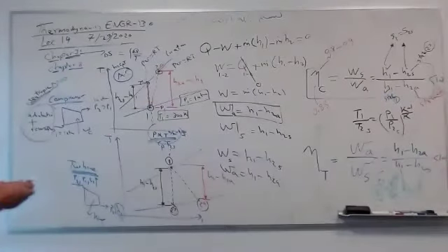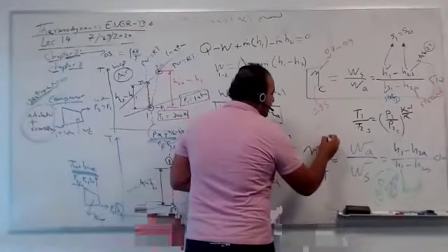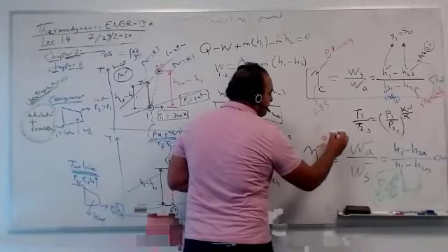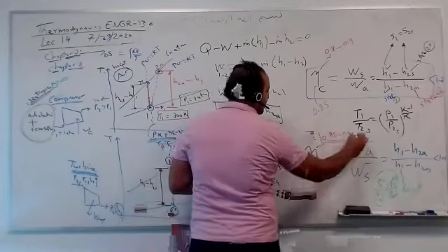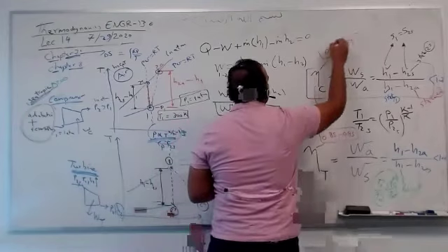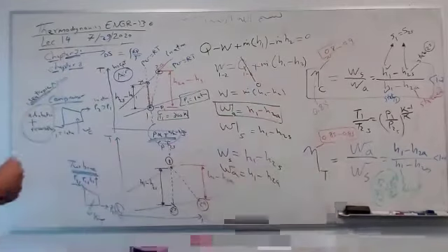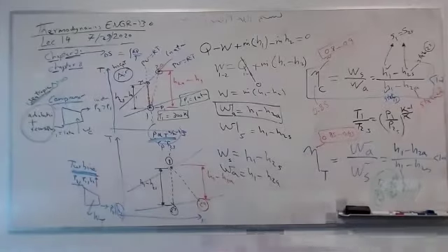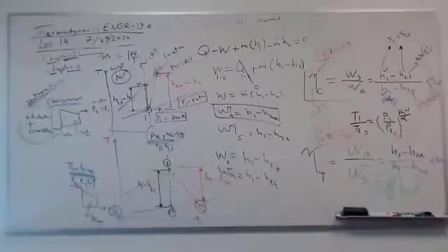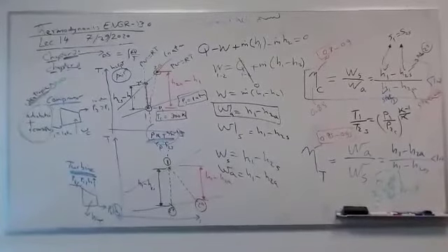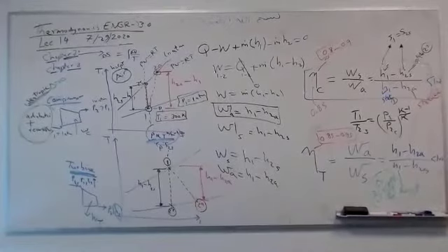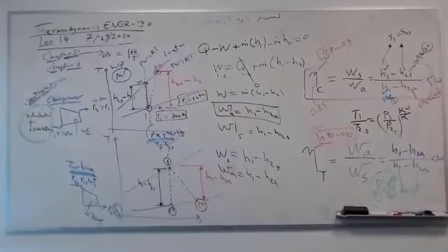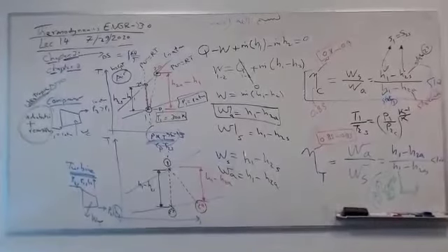The typical efficiency for a turbine is from 0.85 to 0.95, or sometimes 0.98. So this is a much higher range than this. Much better. So it's better to let the flow drive your machine. It's hard to compress the flow. It's easy to expand the flow. When you pump flow into, let's say, a balloon, it's much easier to expand it than compress it.